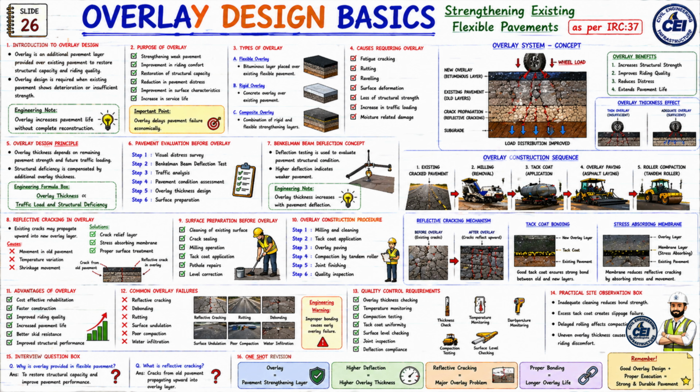Now let us look at the 15th topic. 1. Interview question box. Q. Why is overlay provided in flexible pavement? Answer. To restore structural capacity and improve pavement performance. Q. What is reflective cracking? Answer. Cracks from old pavement propagating upward into overlay layer.